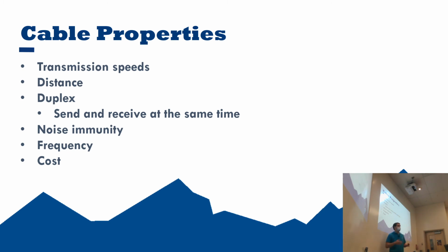You also have to think about how much it is going to cost to terminate each of the ends. How much is it going to cost for us to make ports? How much is it going to cost to do splices? All those are things we have to consider. So that's going to be very important. Frequency is going to be important as well. Let's say that we have some data that needs to be done very quickly. Well, obviously, we're not going to be using Cat 5 for that, so just make sure to keep that sort of stuff in mind. Noise immunity.